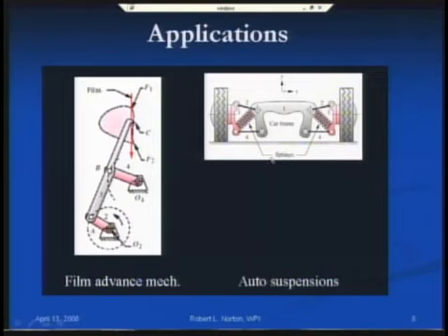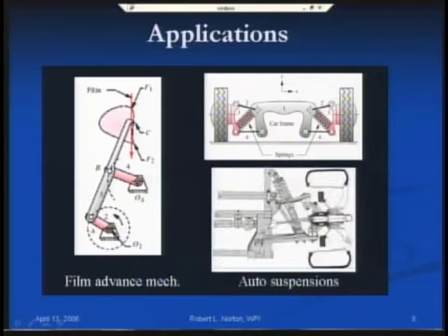So there's no need to have a Grashof linkage here. The spring and shock absorber not shown are what control its motion and keep it from going all the way up. But in fact, the path of motion of the tire as it traverses bumps is along a coupler curve, actually a whole family of coupler curves, because each point on this coupler, as you now should understand, has a different coupler curve.